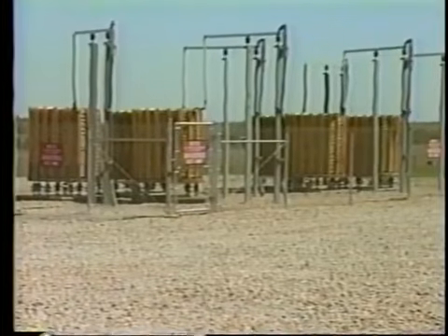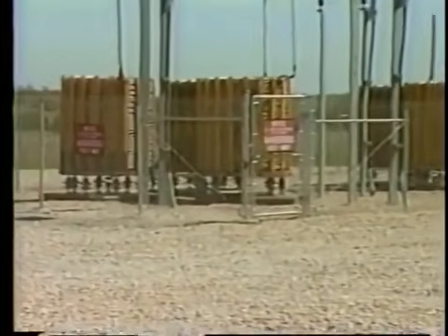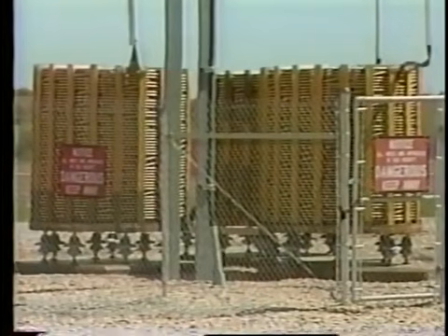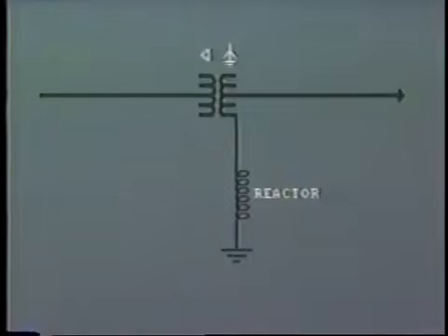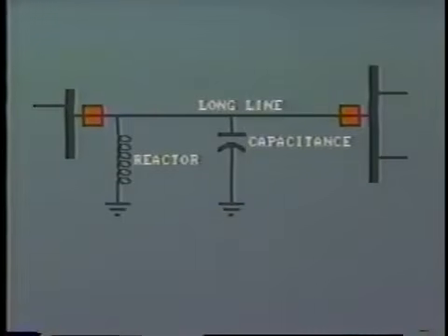Now at this point, let's extend our overall view of transformer protection to include reactors. This is because there are many similarities in construction and therefore protection is also similar. Generally, reactors are air-cooled or oil-immersed, single or three-phase windings on an iron core. Where is the reactor installed? Well, typically in a grounded neutral to limit fault current, between buses to reduce magnitude of current flow, or shunt connected between line and ground to compensate for capacitance on long lines and prevent high voltage levels.